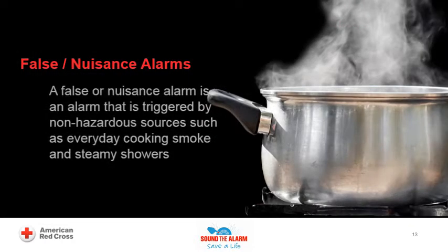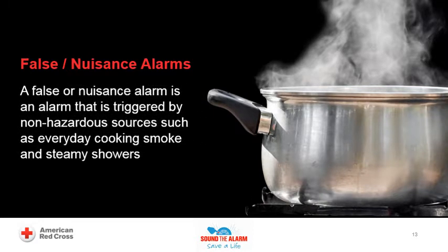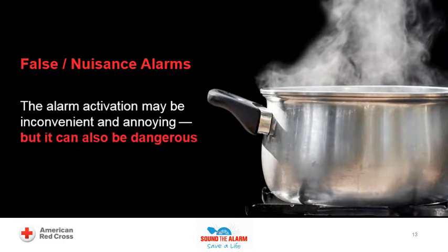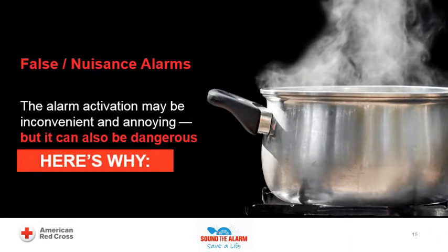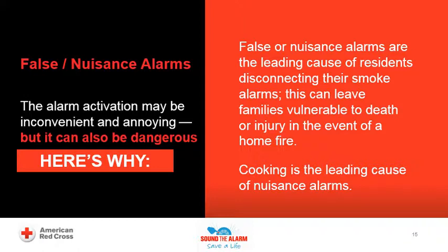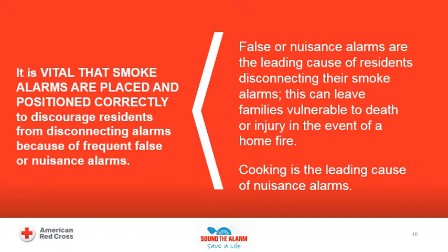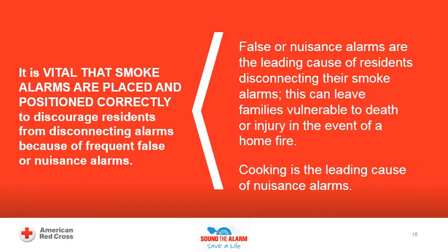A false or nuisance alarm is an alarm that is triggered by non-hazardous sources such as everyday cooking smoke and steamy showers. The alarm activation is inconvenient and annoying, but it can also be dangerous. Here's why. False or nuisance alarms are the leading cause of residents disconnecting their smoke alarms. This can leave families vulnerable to death or injury in the event of a home fire. Cooking is the leading cause of nuisance alarms.